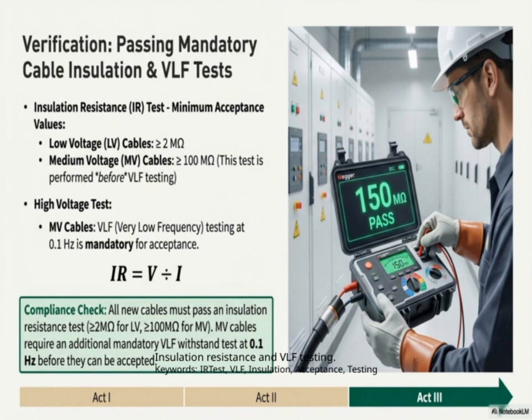Next, we have VLF, or very low frequency testing. VLF is particularly useful for testing large or complex insulation systems, especially in high-voltage cables. It applies a low-frequency voltage to the system, allowing us to detect potential faults or weaknesses that might not show up with traditional testing methods.